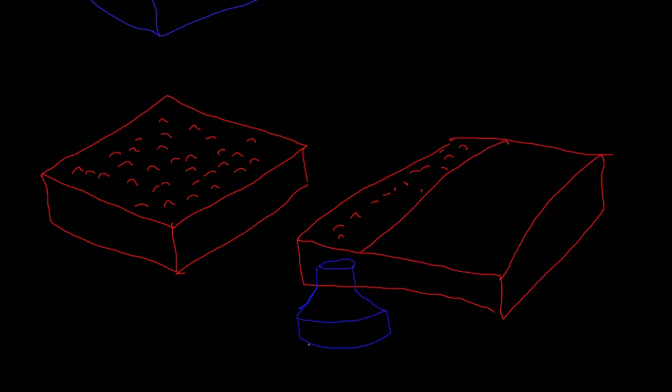And you can't see those carbide cutting inserts because it's rotating at a pretty high velocity. You would calculate the spindle speed, but anyway, you would come across, and by the time that you came across, this whole portion here would be nice and flat, and would be very smooth and very flat by the time that the face mill comes across.